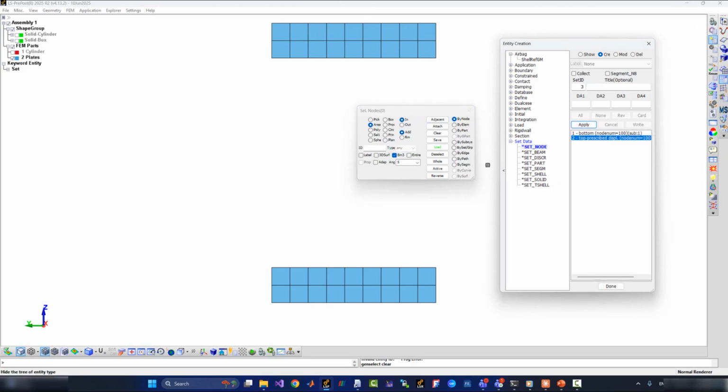Okay. Then I'm going to create a third nodal set, let's call it top bottom plate. So this is the top face of the bottom plate. I need this again for one of the two tie constraints at the bottom of the cylinder that we have to define. These are the nodes on which we will actually assign to node set with ID 3. And let's click on apply.